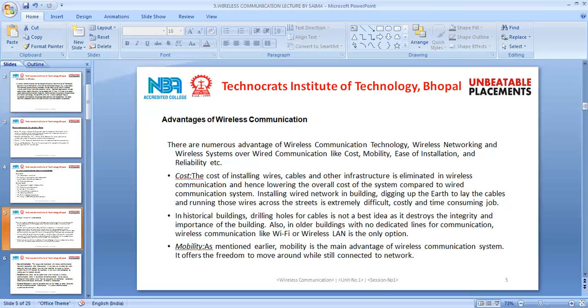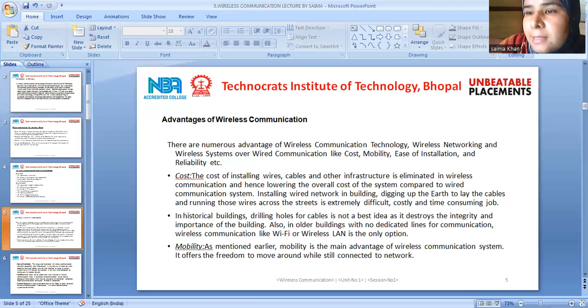Also, ISI, intersymbol interference, in a system with large bandwidth and thus good resolution in the time domain. The major consequence is signal dispersion. In other words, the impulse response of the channel is not a single delta pulse, but rather a sequence of pulses corresponding to the different multipath components, each of which has a distinct arrival time. In addition to having a different amplitude and phase, this signal dispersion leads to intersymbol interference at the receiver.